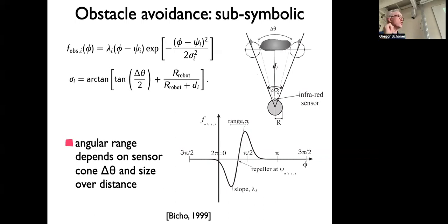Now the range has a subtlety. So the range is first of all, of course, specified by the properties of the sensor. We actually put a little bit of rubber around the emitter so we could control how widely the light is spread, roughly. And that was, I believe, about plus minus 15, so 30 degrees approximately.